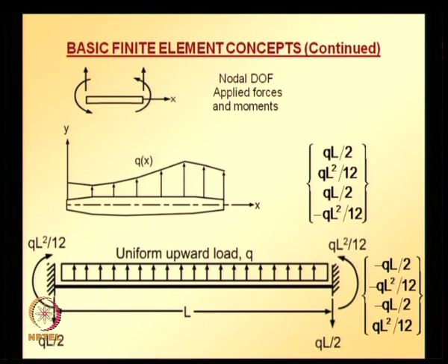That gives us the equivalent nodal loads for finite element calculations. So this physical interpretation is useful in developing equivalent nodal load vectors for more complicated distributed load patterns.